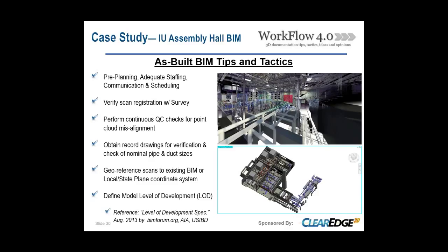Verifying your scan registration with survey is paramount, especially when you're chunking up a job due to customer request to phase the job. Any twist or misalignment, you've now put forth a lot of effort modeling Revit families that are in the wrong position, and we all know that's not easy to undo. You're essentially starting back over. So having that robust QC process is really going to save you a lot as you proceed forward.